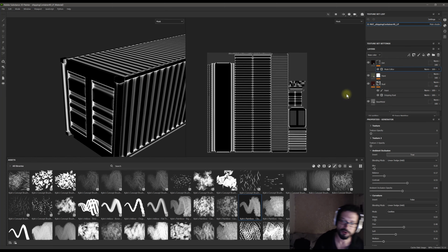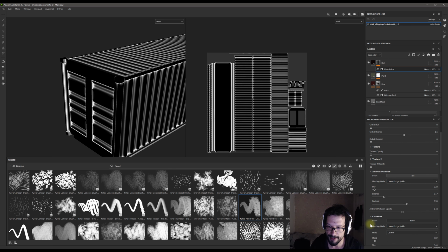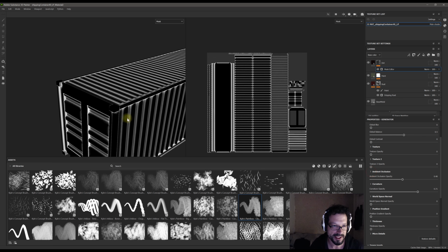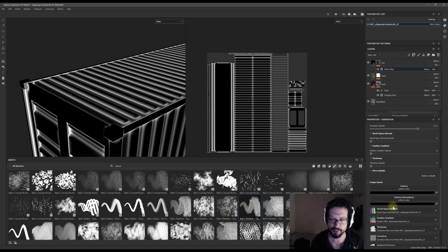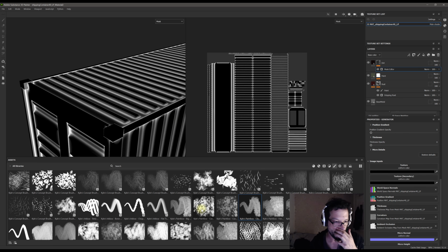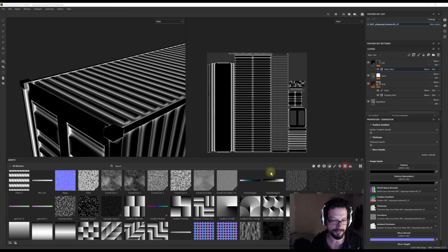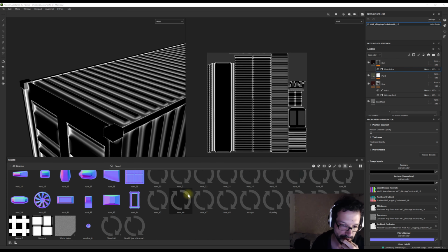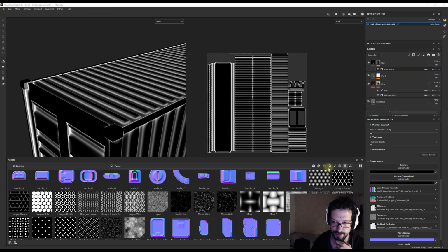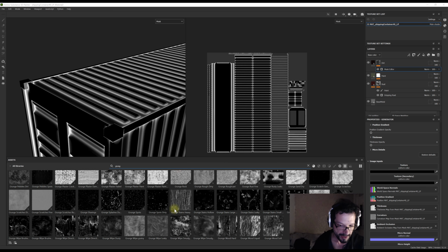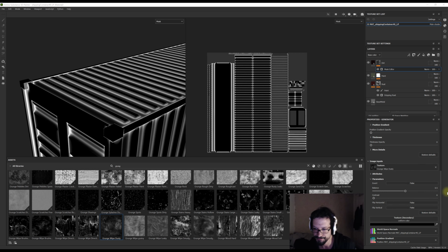I'm not going to show you the result yet, but we're going to introduce yet another texture. I'm happy with the curvature and ambient occlusion, but once again, this is too uniform, and I want to break apart that uniformity. So let's go to textures again, and under the textures, let's go to grunge. So are these the textures? Yes. Under grunge, we have wipe smudge, wipe brushed effects, wipe dusty. Wipe dusty is good enough for me, so I'm going to plug this into texture.